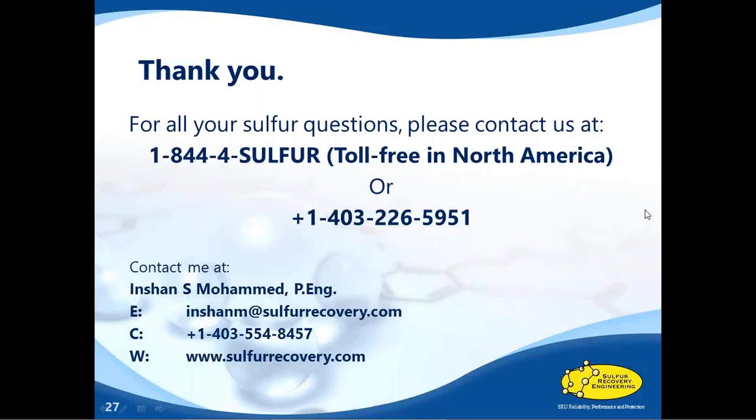Hi, Shashank. Okay, so as I mentioned before, during a particular steady state run or stable run, we took a pressure profile across the plant for those conditions. For each location where we took a pressure reading, we considered that as one block, and in that consideration we included the pressure drop across the equipment plus the piping pressure drop from one block to the other block. For example, condenser one outlet to converter one inlet is considered one block.